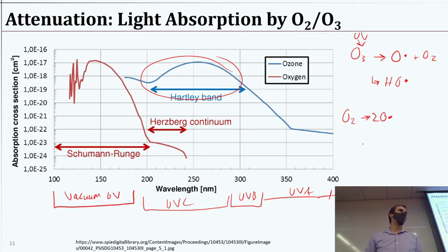You can potentially split water, yeah, but one thing that happens in the atmosphere as well is you do form ozone from oxygen, and vice versa. There's cycling and stuff, but the point being, if you have a strong UV source that you're using in a facility or in a lab, you actually do want to be concerned, because you don't want to generate a bunch of ozone and then have people exposed to high ozone concentrations by accident.